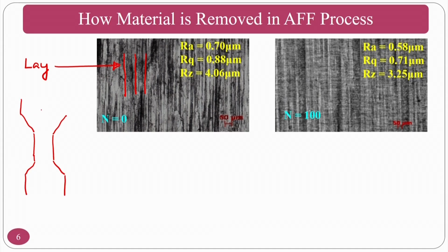So what will happen here is, whenever you reciprocate the medium, the medium flow direction will be like this. So always you place the grinding marks perpendicular to it. That means for your workpiece, if I adjust for understanding purposes, the grinding mark should be like this.